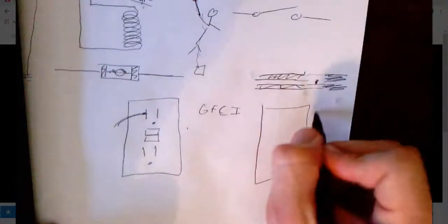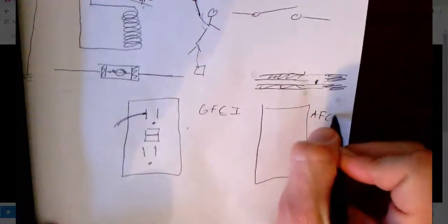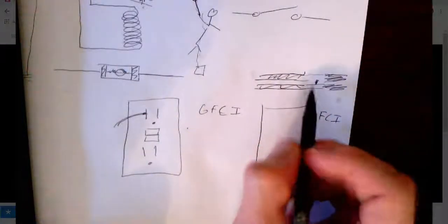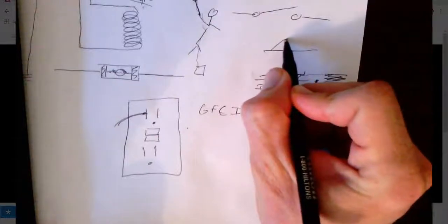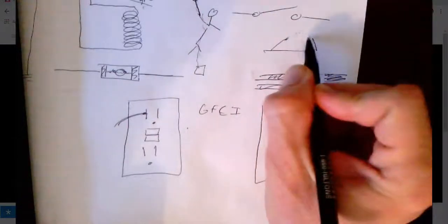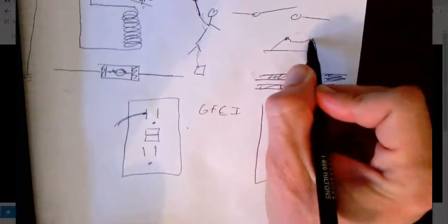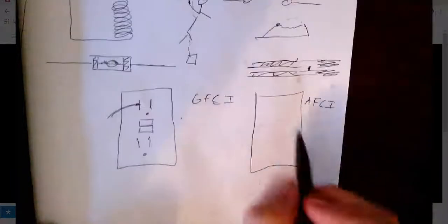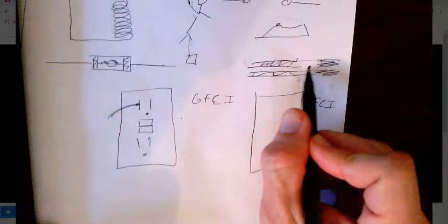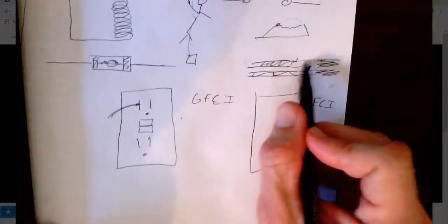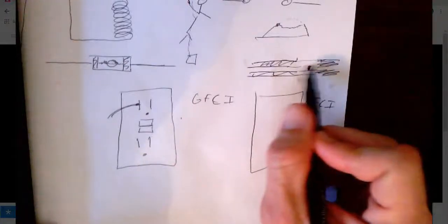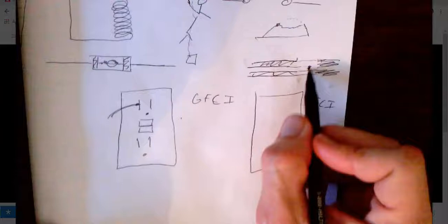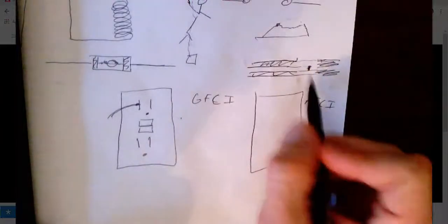And there's something else, arc fault, I think it is, arc fault circuit interrupter, and it's just similar to this, but it's worrying about this making arcs every time the voltage goes high. It's going to make a little arc, and the voltage won't keep going up like it should. Okay, it'll be like, make an arc. And this thing watches out for that, because sparks in the wires, a little lightning bolt in the walls of your home, if somebody drilled through and scraped these, they didn't drill through them enough to break the circuit, but they drilled through and exposed the bare wire here. It can make lightning bolts called arcs in your wall, and that can start a house fire.